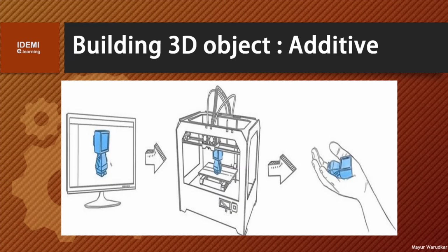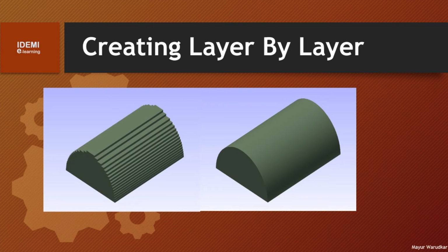Suitable for use with a range of different materials. The cartridge is loaded with the relevant substance and this is printed into the shape, one wafer-thin layer at a time. These layers are repeatedly printed on top of each other, being fused together during the process until the shape is complete. Since the process is layer by layer, the actual output of the product can be like image 1 even if the input model is image 2.